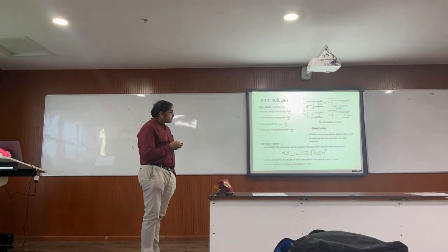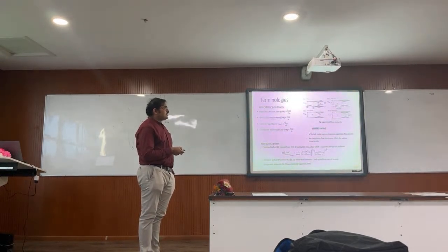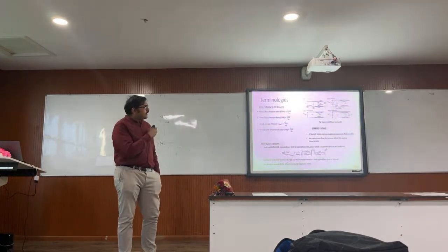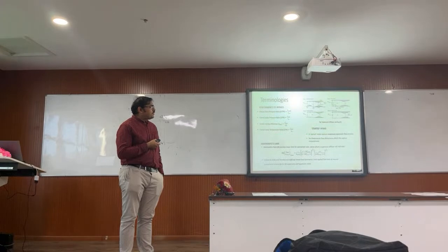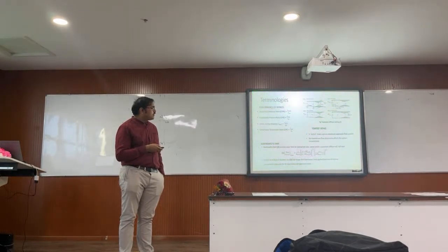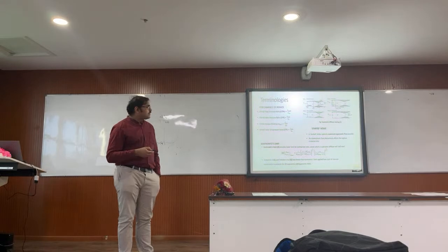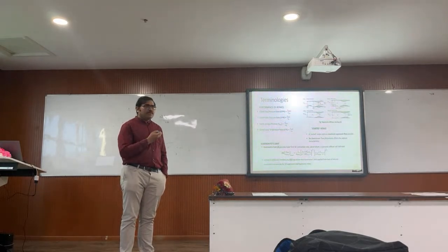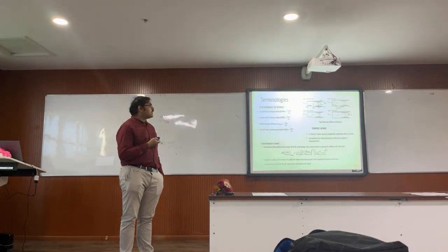And when we look at, as I told you, what is a started intake? A started intake is something which takes in whatever mass it is designed for and gives it to the combustor. And during this operation, the entire flow path in the diffuser region, at least in the forward portion, that is the upstream portion of the diffuser, is supersonic. And we know that supersonic flows do not allow upstream propagation. So downstream changes do not affect mass capture characteristics. Okay. So again, I'm assuming some things are known to you. If you have some doubts over here, you can always stop and ask.